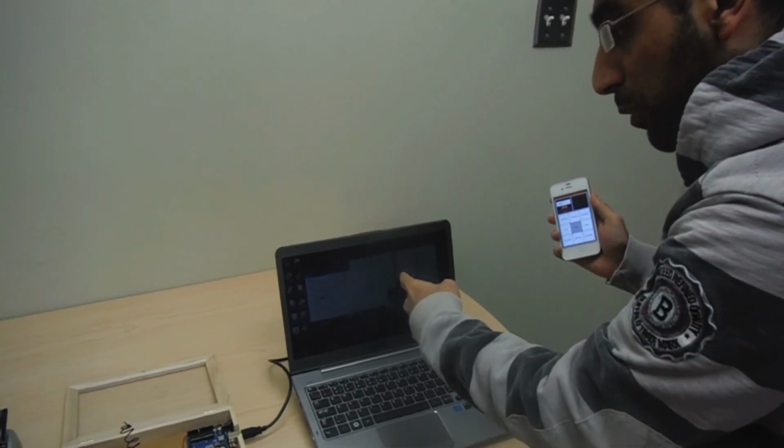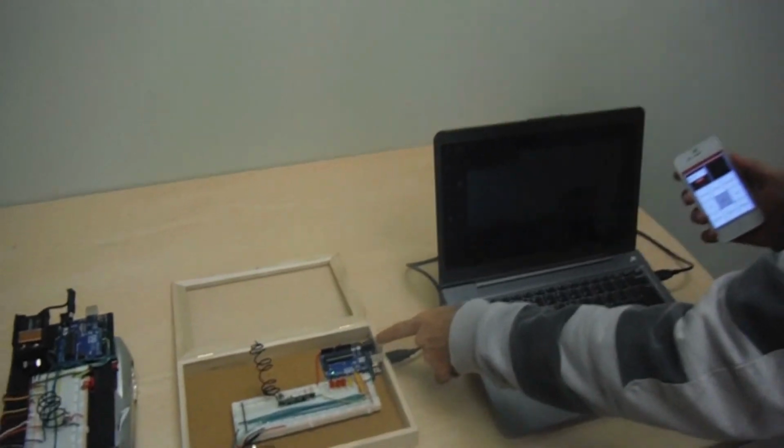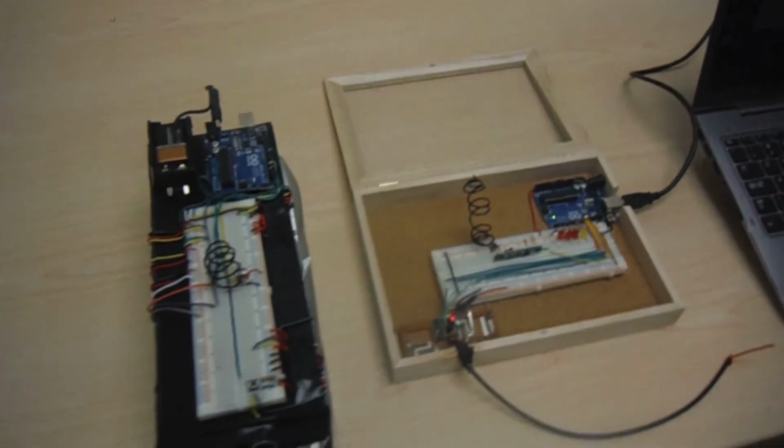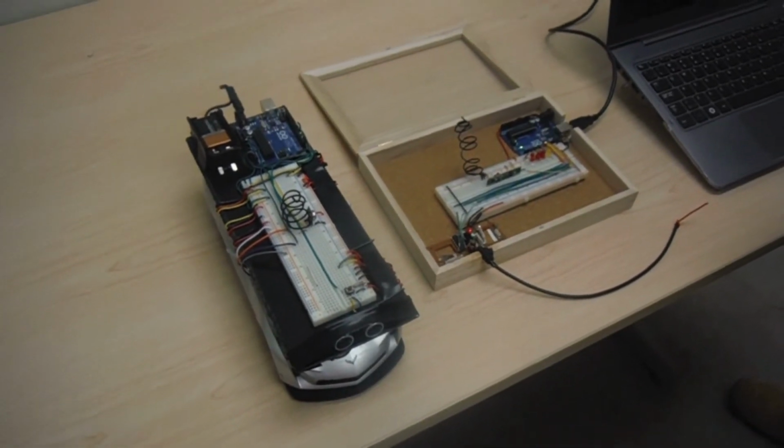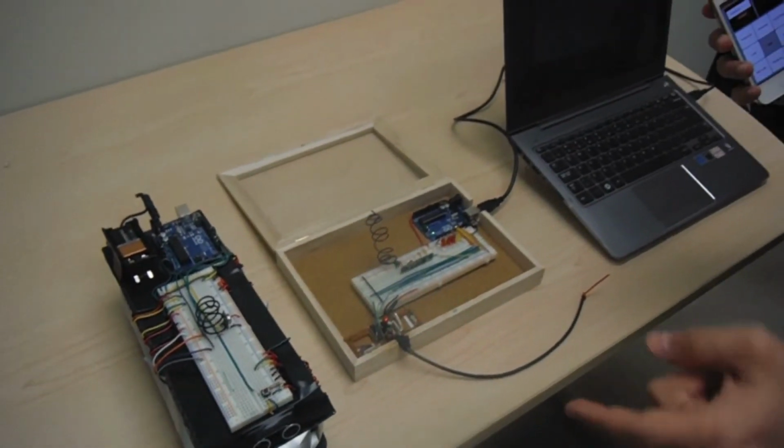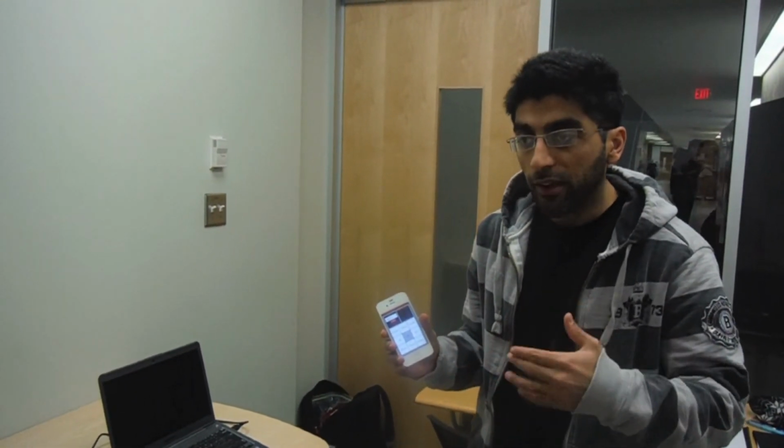That information is processed, sent back to the downlink microcontroller, which then shuts off the power to the forward motion of the car as collision detection, and then pulses the reverse to break the momentum. So this entire process of downlink and uplink that I just talked about happens every millisecond.